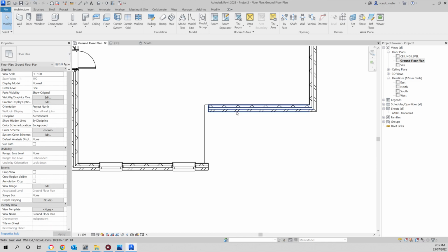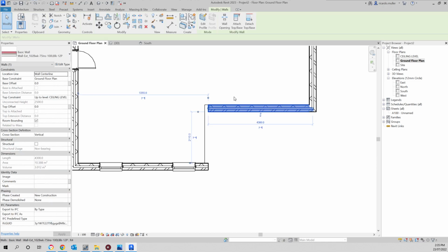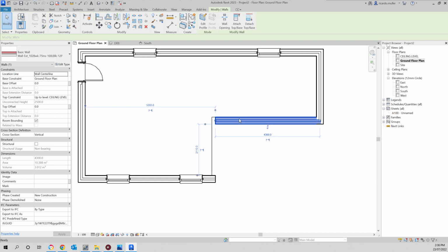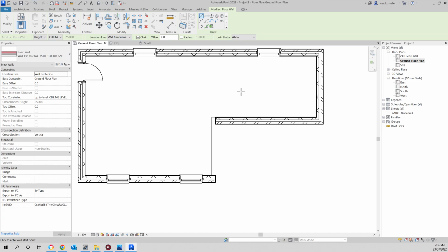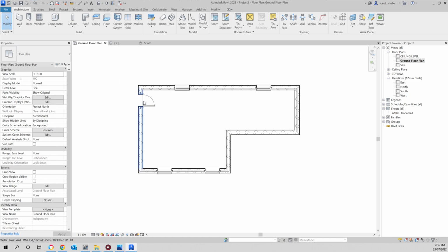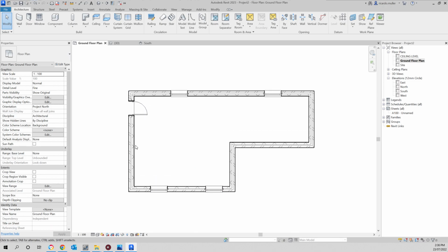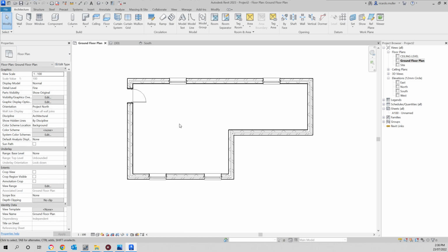To do so, I'll click on an existing wall element like this one here. I'll press the keys CS. CS is create similar, okay? I will click on there and then back there and it's back. Notice how the floor actually moved with that wall, which is really interesting. So Revit is quite smart in that it can make these guesses. Sometimes they're helpful, other times not so much. So hopefully they help us most of the time.